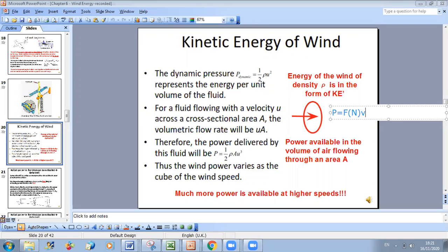But this formula is used if you are displacing a certain body at a known velocity V. On the other hand, what we have here is the pressure, in Newton per meter square. Then to obtain the unit of power, you should multiply by the volumetric flow rate, Q dot. So we should multiply by Q.